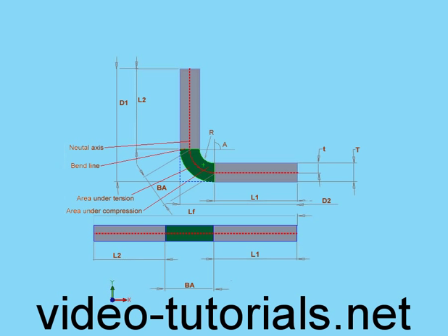If you compare the length of this part in my example here, before and after the bending, you're going to find that they're different. As engineers, if we don't compensate for this variation, the final product won't have accurate dimensions. Of course, this is more critical for parts where you've got to maintain a tighter allowance or precision.